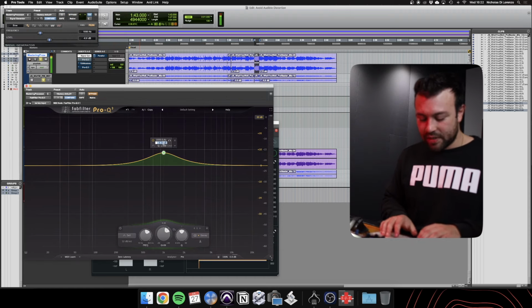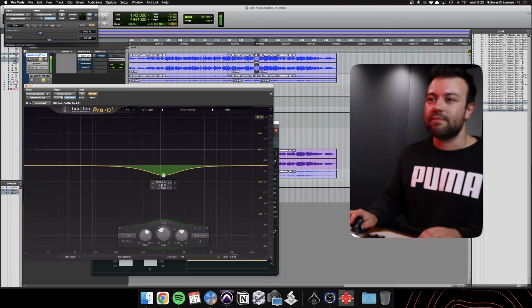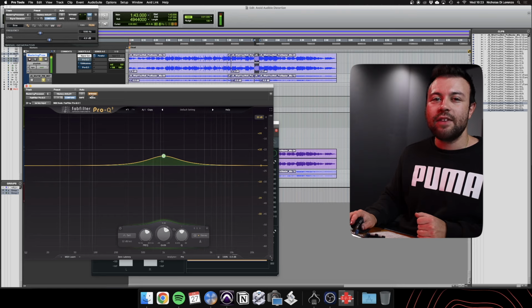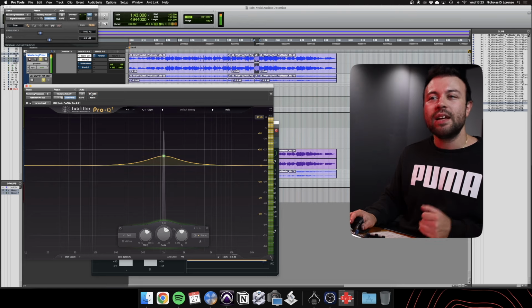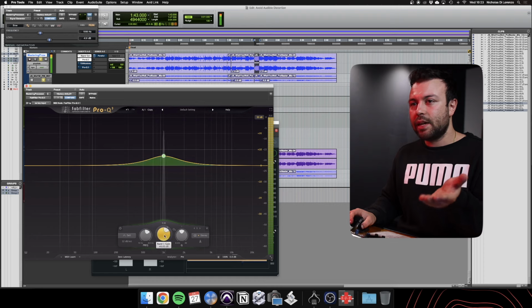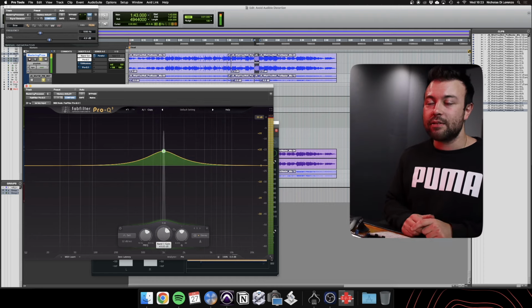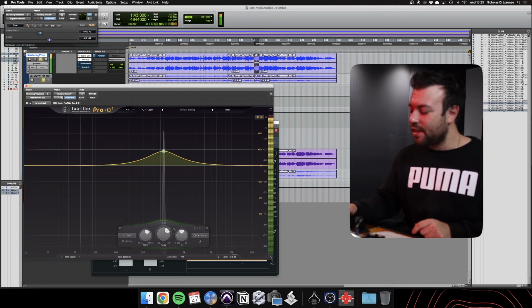I'm going to make it negative 6 decibels full scale as well. So we're going right up to the ceiling where it is there. And if I bypass this and put this EQ in, the sine wave is still going to be clean. It hasn't gone over 0 yet. However, if I make this 9 decibels, can you hear those harmonics?